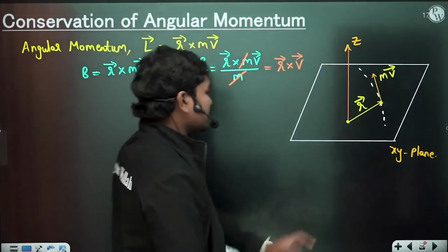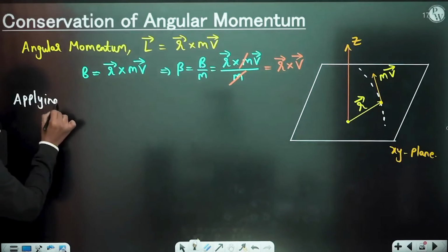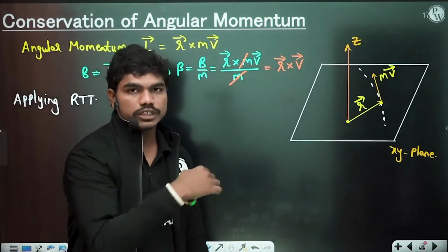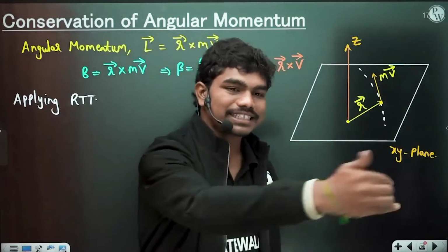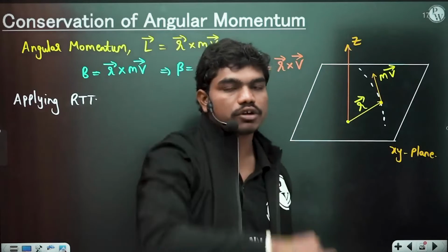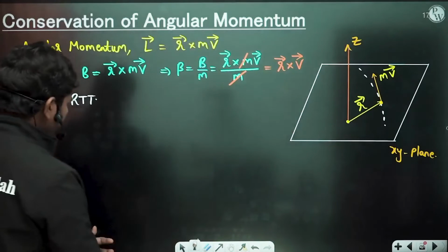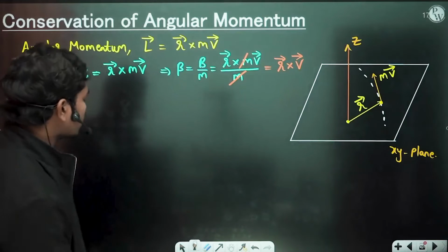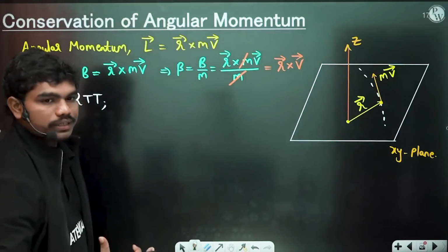Now apply Reynolds Transport Theorem again. So applying RTT, let us suppose there is some fluid which is going through some evolution. Normally in the case of turbines and pumps, in case of radial entries, fluid actually rotates. Fluid will enter radially, rotate and leave out. In turbines generally we have this, and also in cases like lawn sprinklers, which are like radial flow reaction turbines. Now if you apply this Reynolds transport theorem, let us see what comes out.